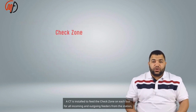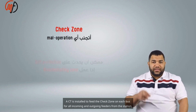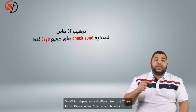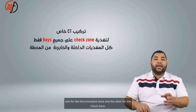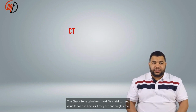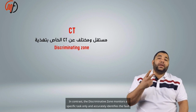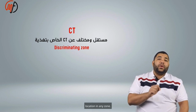A CT is installed to feed the check zone on each bus for all incoming and outgoing feeders from the station, except for the bus section and bus coupler. This CT is independent and different from the CT used for the discriminative zone, so each bus has two CTs, one for the discriminative zone and the other for the check zone. The check zone calculates the differential current value for all bus bars as if they are one single area, monitoring the entire system at once, but does not identify the exact fault location. In contrast, the discriminative zone monitors a specific zone only and accurately identifies the fault location in any zone.